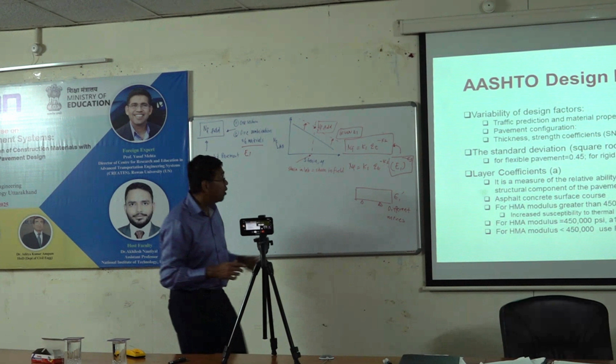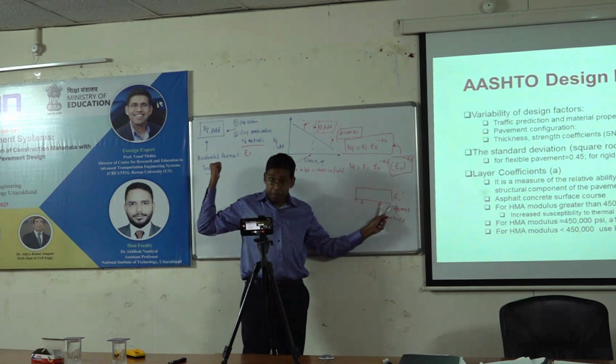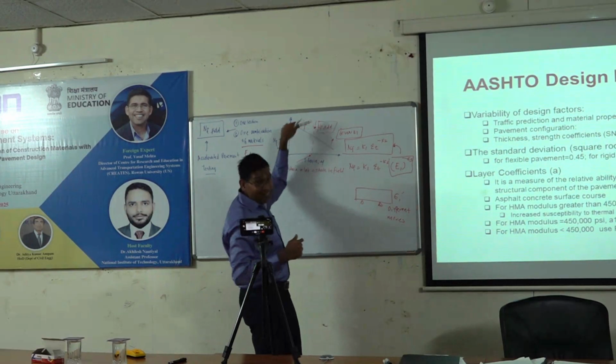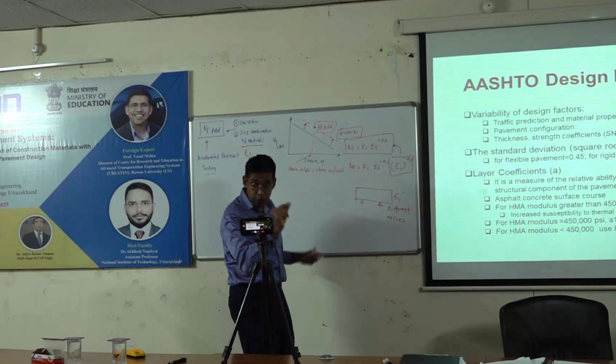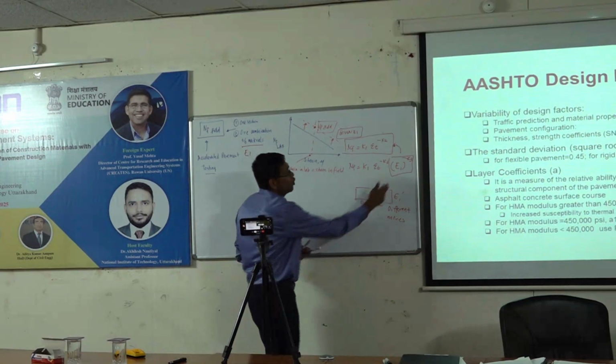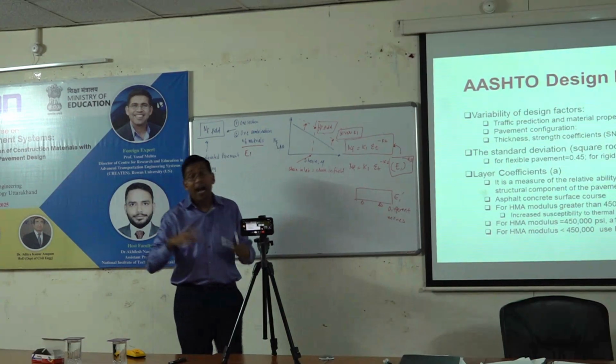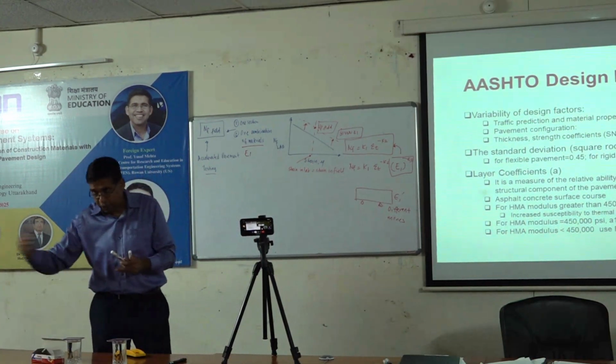But just remember that this was not constructed in the field, there's only one, so you can't calibrate that. There's only one calibration suitable for one E value. You just have to tag on a different E value. Yes, you have to test different mixes, and do beam fatigue tests at a broad range of strain values.